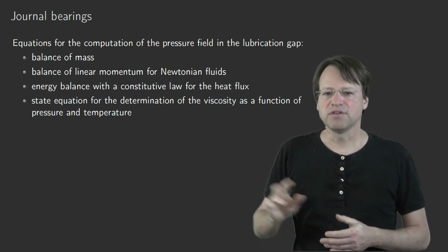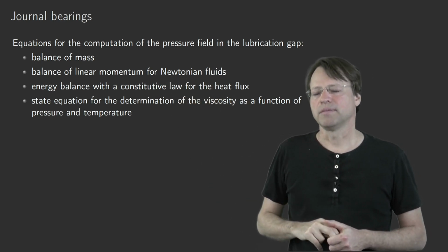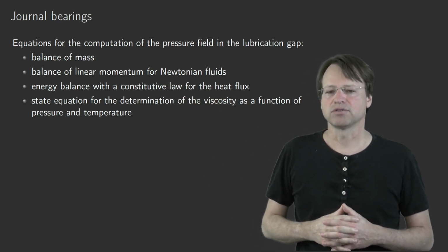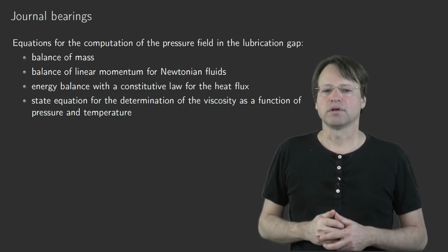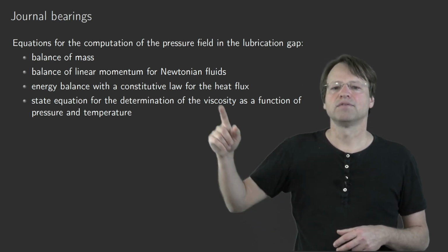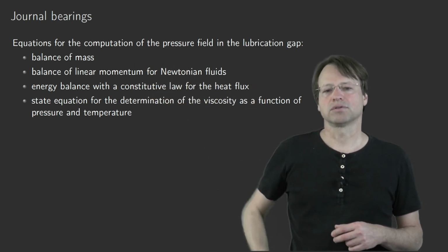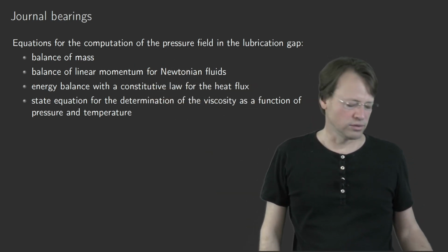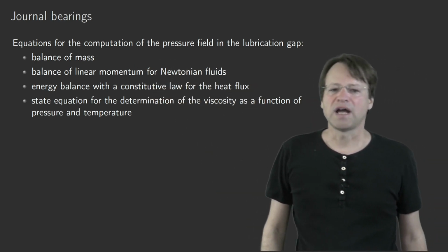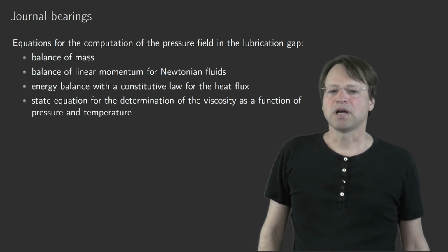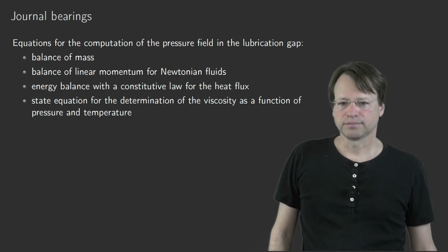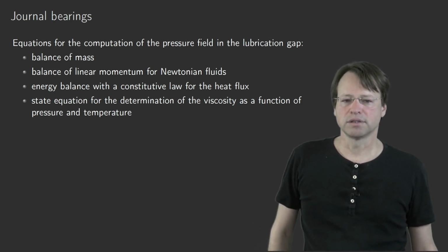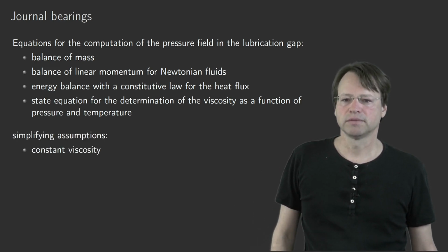So we have to simplify these two equations, especially the balance of linear momentum will be simplified, will be solved then for the velocity field, and then the velocity field is introduced in the balance of mass, and finally we obtain a partial differential equation that governs the pressure. Well, and this is then the Reynolds equation.